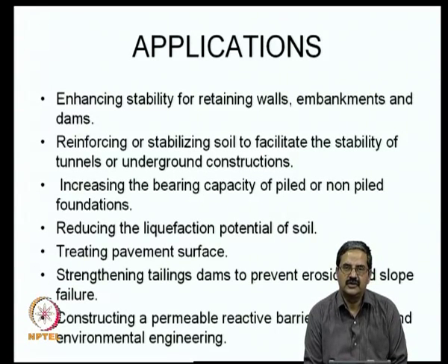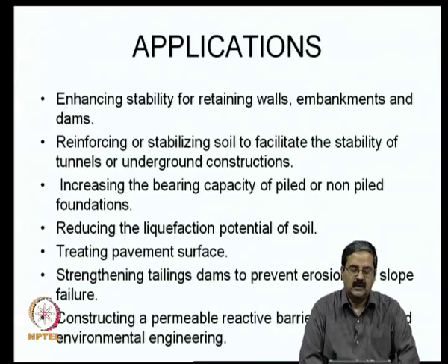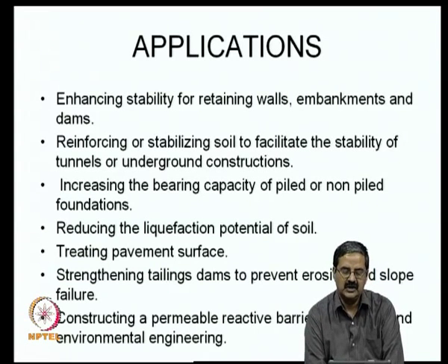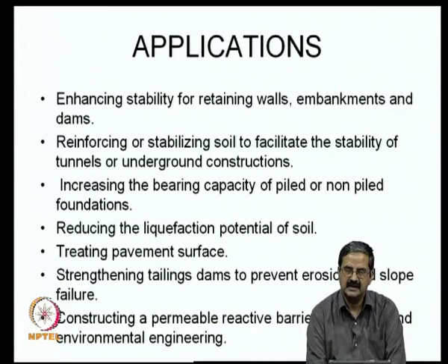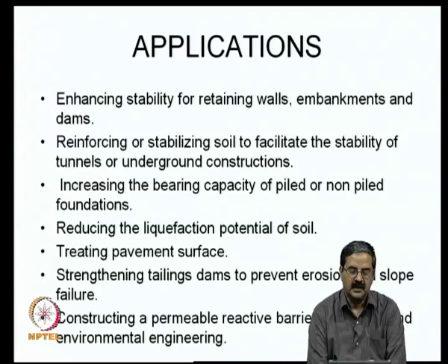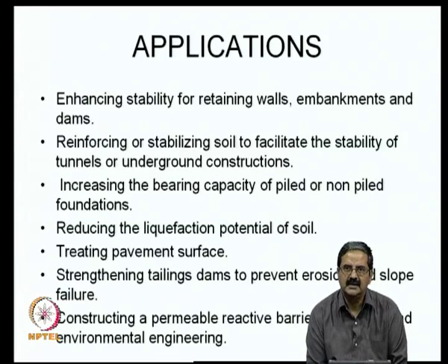And of course, one should design here what is the problem actually, what are the stability calculations that one can think of. If you are looking at retaining wall stability, embankment stability and dams, you should make a lot of calculations, and if the parameters do not satisfy these stability requirements, then you need to go for improvement.